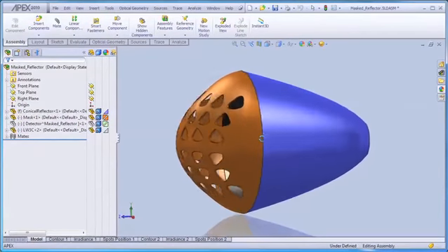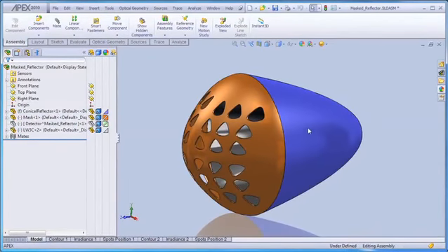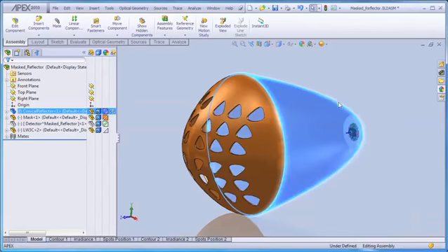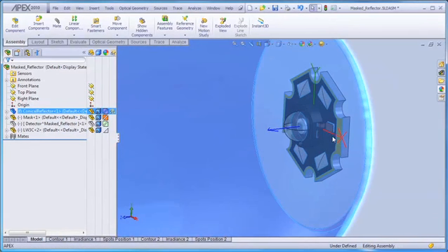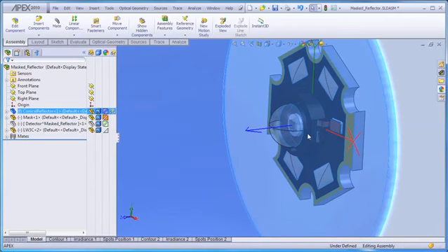Now, using the Apex Light Source Manager, we can quickly insert and position an LED into the model. We can assign total power, wavelength, and number of rays before creating the LED source, and note the level of detail included in the LED geometry.